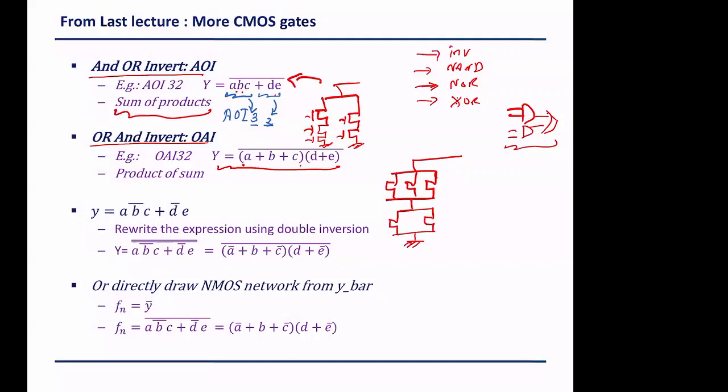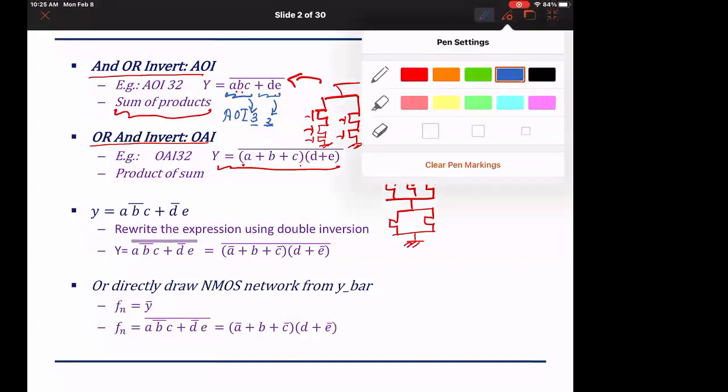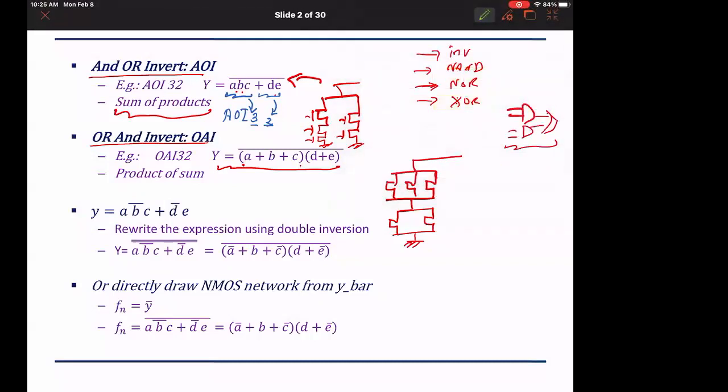Now let us look at the lower gate. And in this lower gate, which is OR times AND and inverted, I have 2 products, 2 sums, sorry, with a product of these sums. So this is an OR at the innermost, then it's an AND of all of these sums, okay, and then I have the inversion. I have 2 sums here, so I have 2 entries to fill.